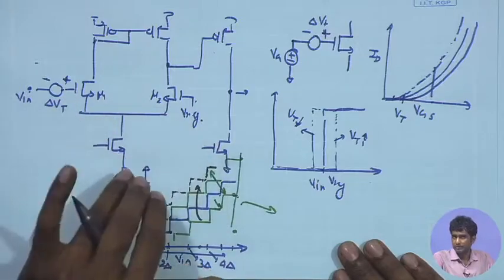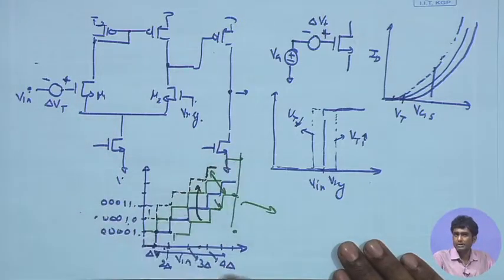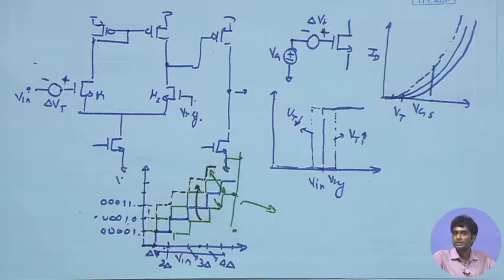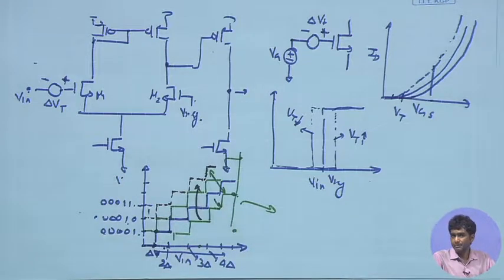It can go to a few tens of millivolts, and in that case our transfer characteristics for the NMOS and PMOS comparators can be different and vary over time, and therefore there will be a time dependent error in the signal that you are recording. So, this is very undesirable, and definitely we would like to have some mechanism through which it can be compensated.